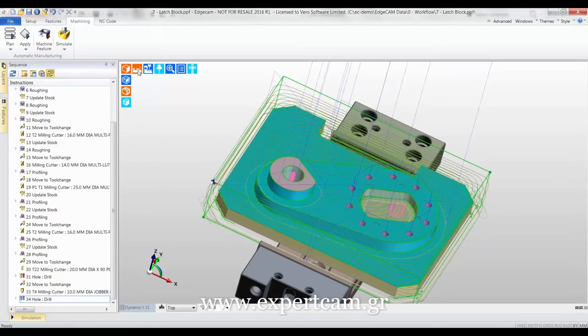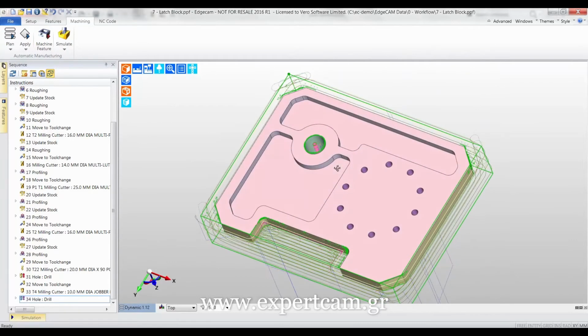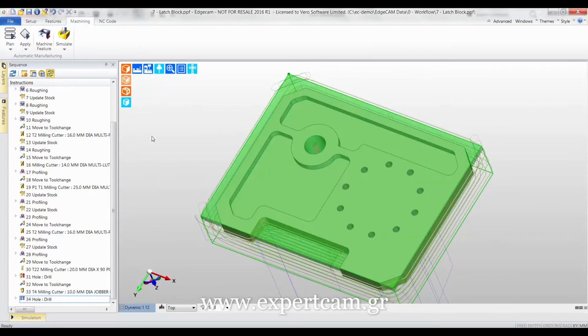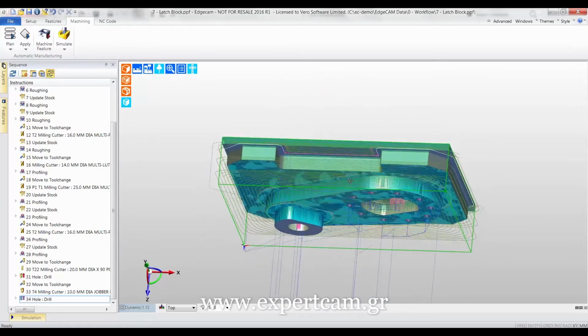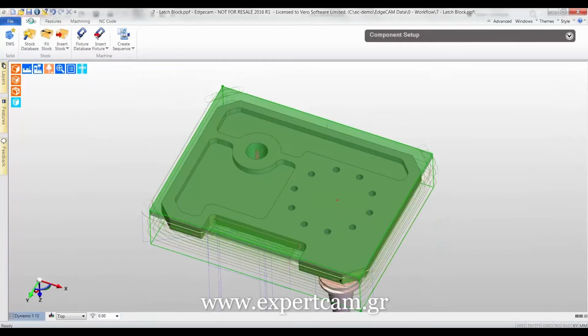In practical terms, our work is only halfway done. How about the underside of the part, or its second end? There are features to be machined on the underside, plus the stock shape needs to be transferred to the second end. Well, we simply repeat the steps previously mentioned.